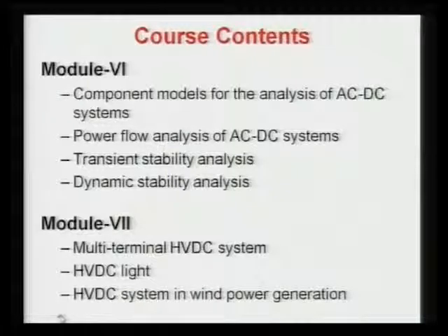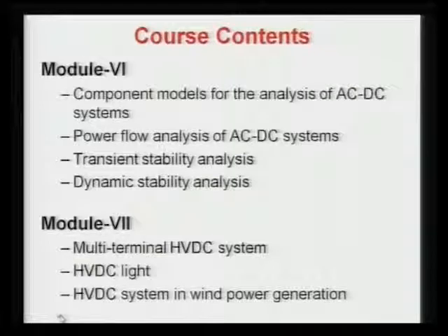here first I will model the various components of AC/DC systems, including the DC, the base powers, etc. For AC and DC, we have to match the AC base power and voltage, and also the DC base power as well as the voltage, and then we will model them in detail, and later go for the AC/DC load flow. Various techniques are suggested, that is sequential based AC/DC power flow analysis, or elimination based or unified schemes. They are discussed in much detail in this module 6.